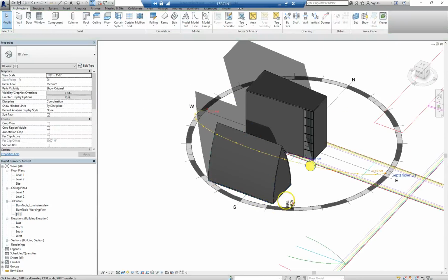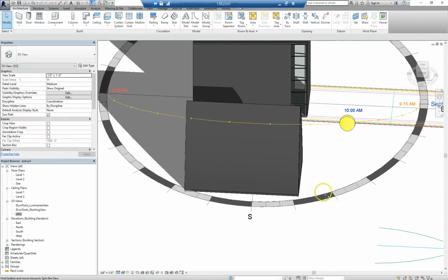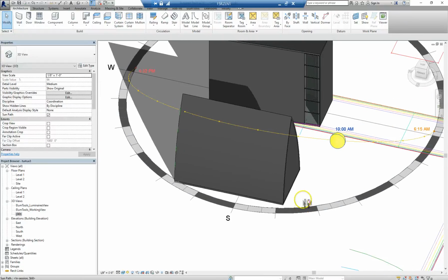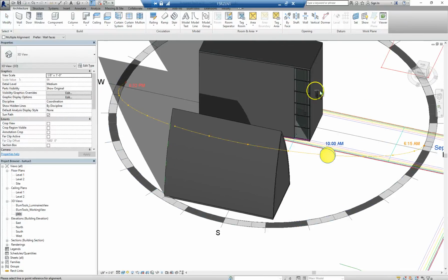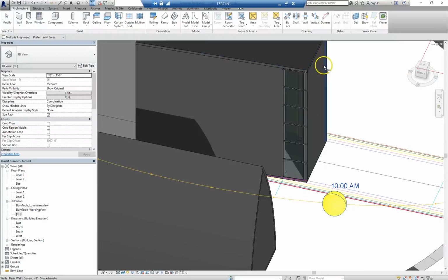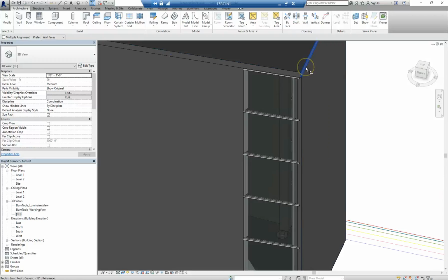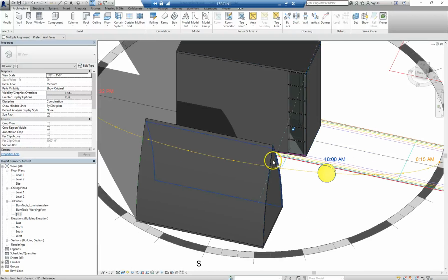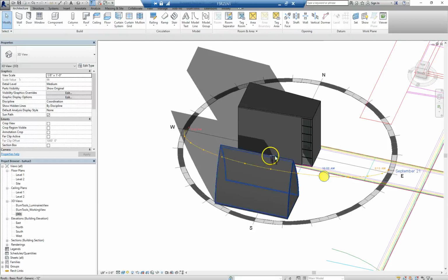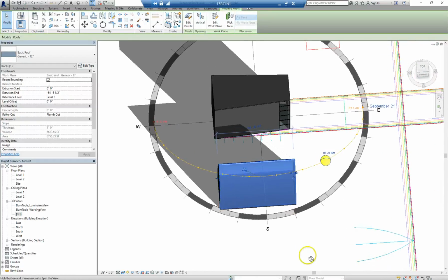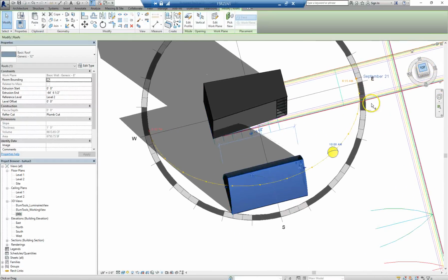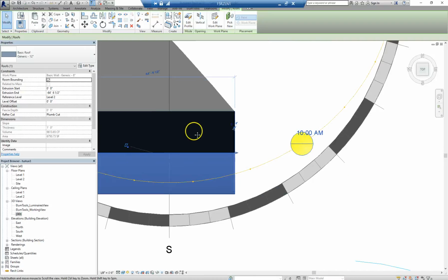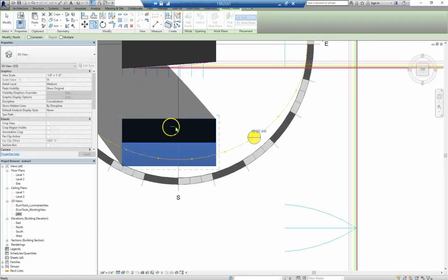What I'm going to do here is we already made a roof. That's the right dimension. So I'm going to kind of just cheat and copy it. Right now I'm doing the align command, and I'm making sure the end of my building's in the same spot. So I'm doing a line and a line, and nothing moves. So it's perfectly the same shape as the building you already made. I selected the shape, go to a top view. I'm just going to copy it.